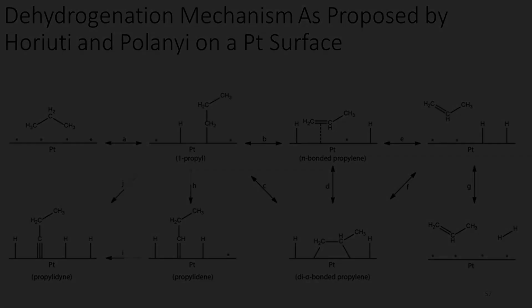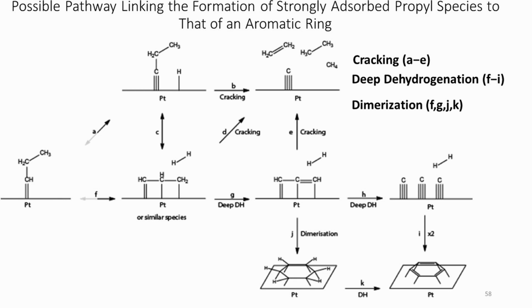All dehydrogenation catalysts deactivate with time on stream, with several processes being responsible for the deactivation of the different types of catalysts discussed in our previous lectures. However, there has been a clear consensus in the literature since the 1970s identifying coke deposition as the main cause of deactivation. The process of coke formation is very complex and not very well understood.